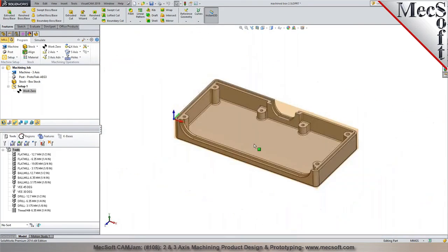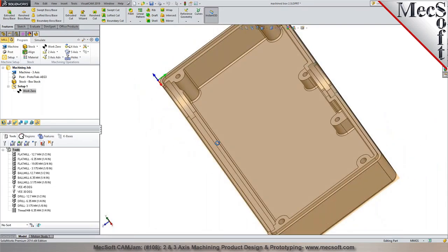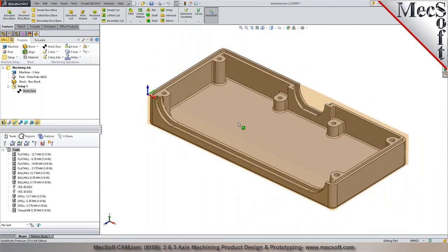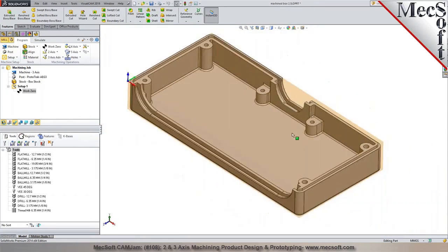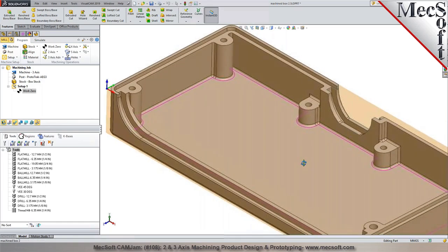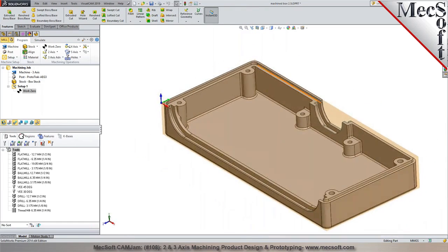In the next step, we're now ready to program toolpaths. So would you like to basically remove all the material inside this cavity, like a pocket? Yeah. Okay. So there are different ways you can program it. For prismatic parts, you could just do a 2.5 axis operation. Here you also have some fillets on the part. We could check the radius here, so you have a radius of 1 millimeter. If you want to just do a 3-axis operation to automatically account for all of these, you can use 3-axis operations to program it.